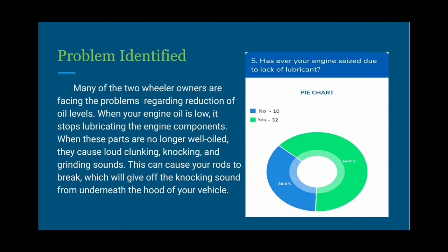This particular slide is dealing with the problem identified. Many two-wheeler owners are facing problems regarding the reduction of oil levels. When your engine oil is low, it stops lubricating the engine components. And when these parts are no longer well oiled, they cause loud clunking, knocking and grinding sounds. This can cause your rods to break, which will give off knocking sounds from underneath the hood of your vehicle. Basically, whenever the oil level in the tank decreases to a greater extent, it directly impacts the health of the engine due to the effect produced by less lubrication of the engine components.